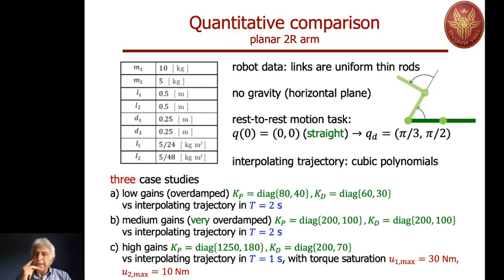The first gain is larger because remember that we use this to drive the torque of the first joint, which needs to move the whole structure, so it sees masses and inertia of both links. So typically the gains of the first joints are larger than the gains of the distal joints in serial kinematic chains.